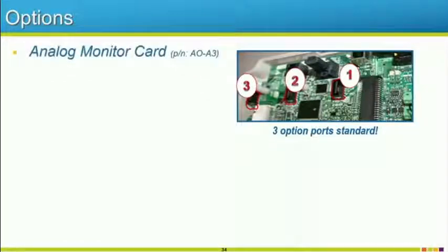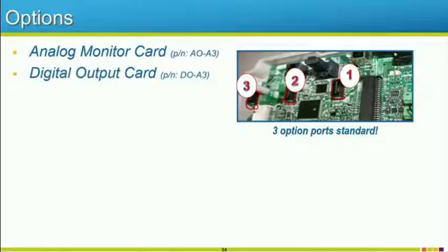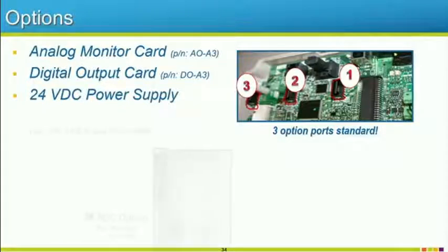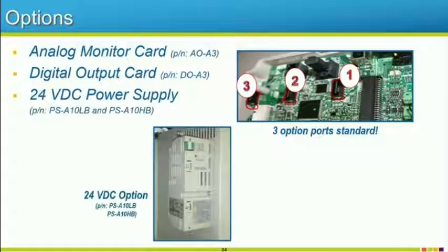An analog output option adds 2 additional analog signals to the R1000 for use with metering or monitoring operation. An available digital output card provides 8 additional digital outputs for monitoring the statuses. The 24-volt control power unit option provides board-level component voltages for the R1000 when provided with 24 volts from an external customer-supplied source. It is used to maintain both drive control power and also network communications.